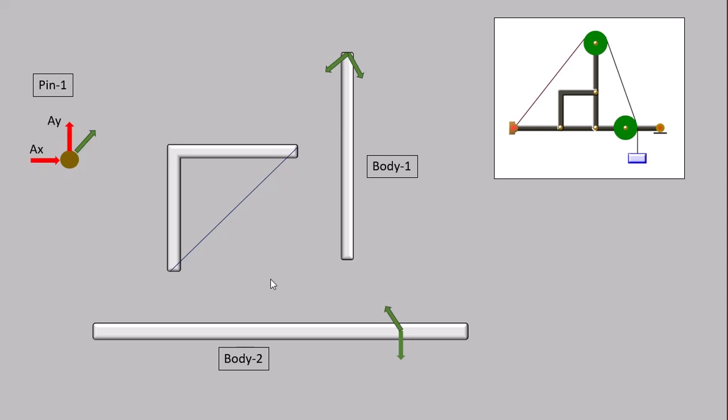Complete the free body diagram. The support pin on the left, and this is the interaction between the support pin and the bottom horizontal member. Two-force member, interaction between the vertical multi-force member and the horizontal multi-force member at this pin.